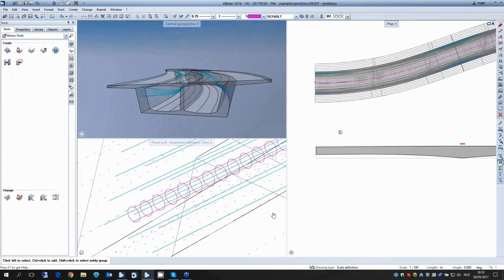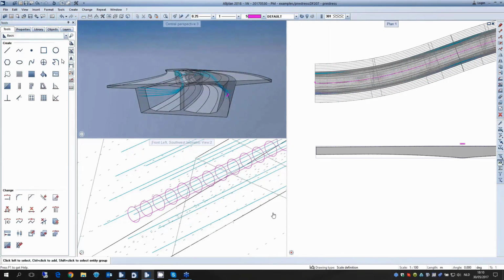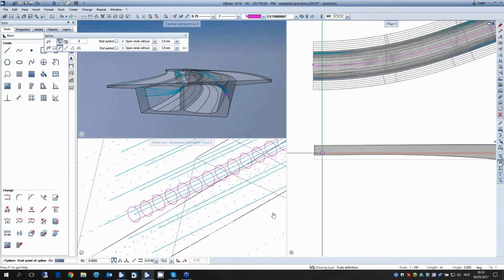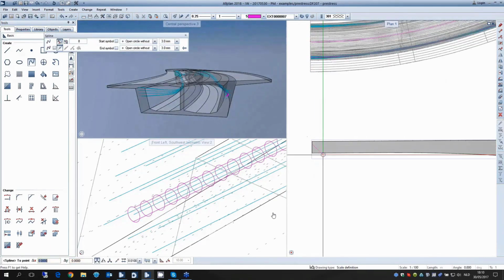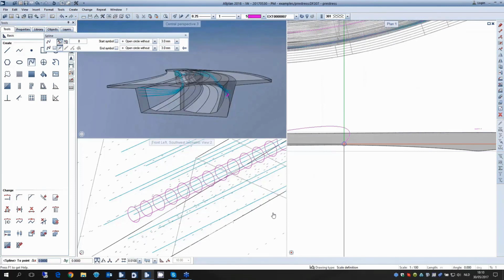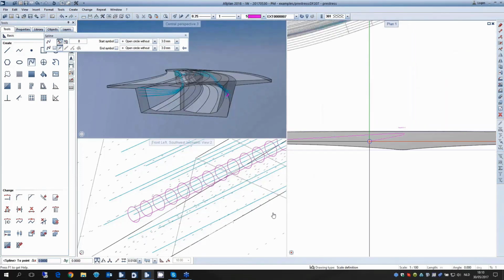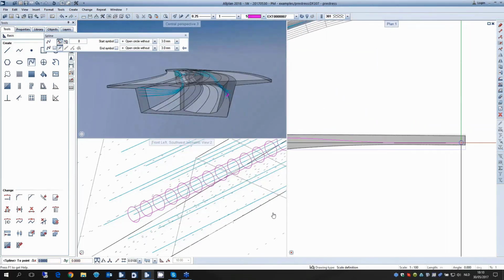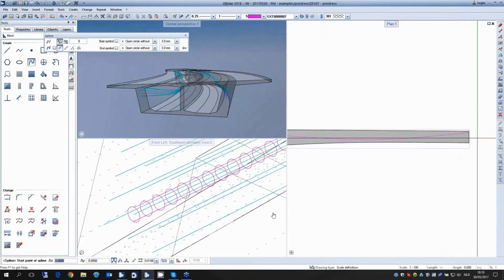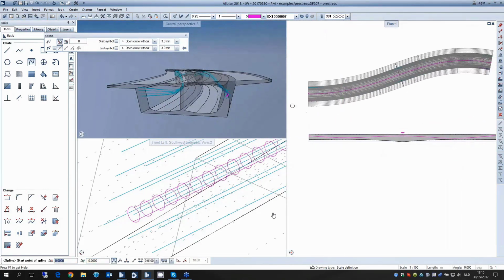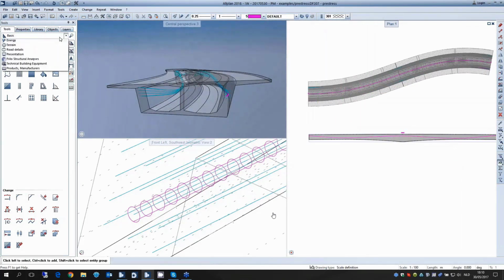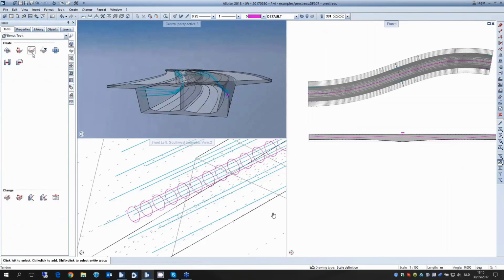In this path, we can begin to find some vertical curvature that we're going to use for our PT duct. This time we're just going to do it freehand with the spline, putting it at the top, at the ends where we have negative moment, and then at the bottoms where we have positive moment, and just freehanding this. Of course, if you're doing this in production, you would want to have some control points to follow for your spline, but here for the purposes of demo, this is good enough.